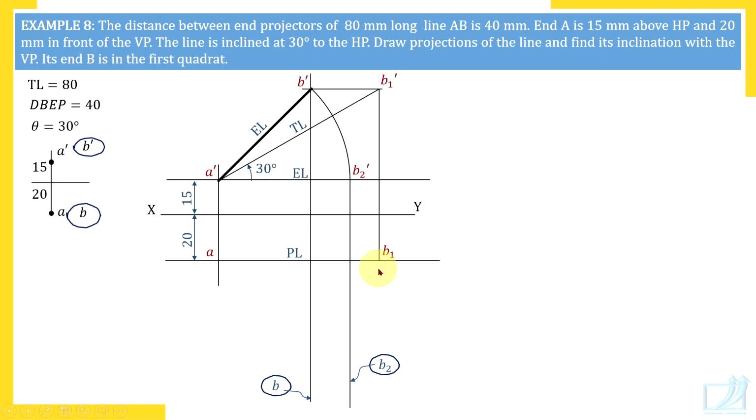Now there are horizontal vertical lines through all labeled points that suggested you to use compass. Rotate either EL or PL, but EL rotation is already over. So now we should rotate PL. So rotate PL, AB1, PL, and AB also has length PL. So by rotating AB1, you will not get B2 here. You will get B. Be very careful about that. That is why these rough labels we use. These rough labels help you to avoid mistakes during the construction. So join A and B.